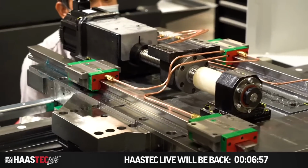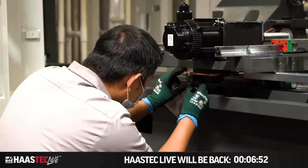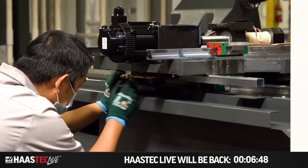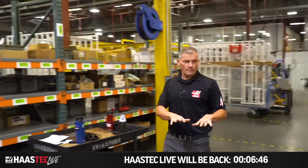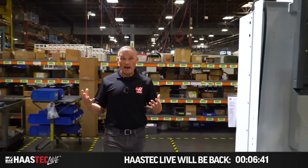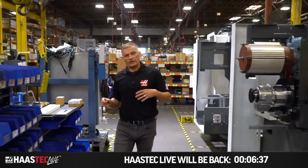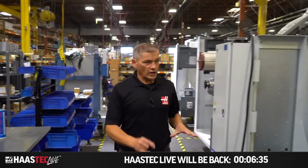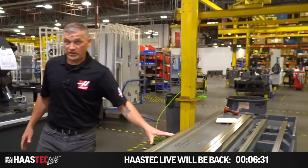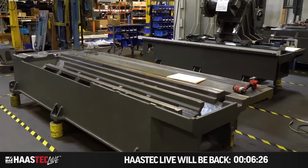Now, similar to the mill line, we have a cast area and a final assembly area. This is the cast assembly area. Kind of the same idea here. You place the base on the ground, put down the linear guides and ball screws, and then you start adding all the large sub-assemblies. In this case, let's get back to this one here. Now you see here, we have a base casting where no assembly work has been done yet. Just getting ready, they'll level this out, then they're ready to put on the ball screws and linear guides.